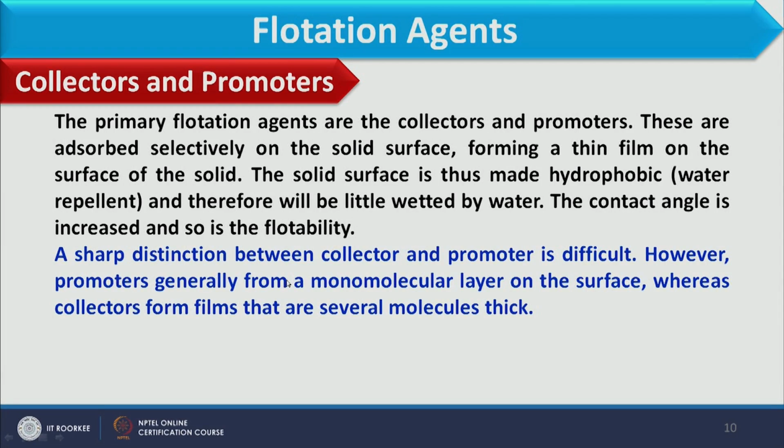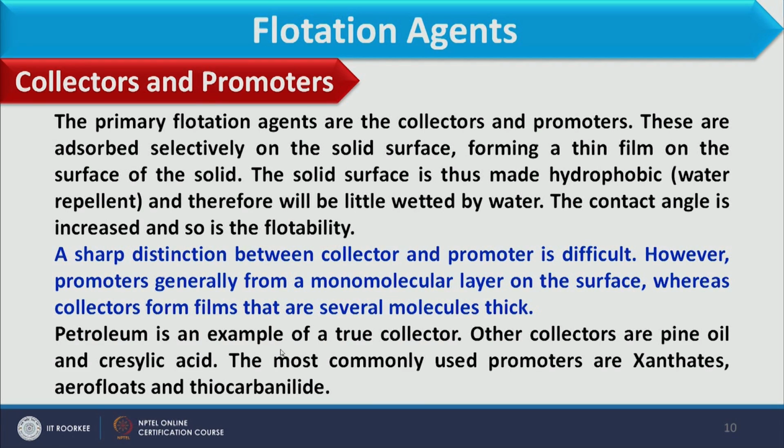So, a sharp distinction between collector and promoter is difficult. However, we can say that promoters generally prepare a monomolecular layer on the surface, whereas collectors form films that are several molecules thick. That is the only difference, otherwise collector and promoter work in the same manner. Petroleum is an example of a true collector. Other collectors are pine oil and salicylic acid. The most commonly used promoters are xanthate, aerofloats and thiocarbanilide.